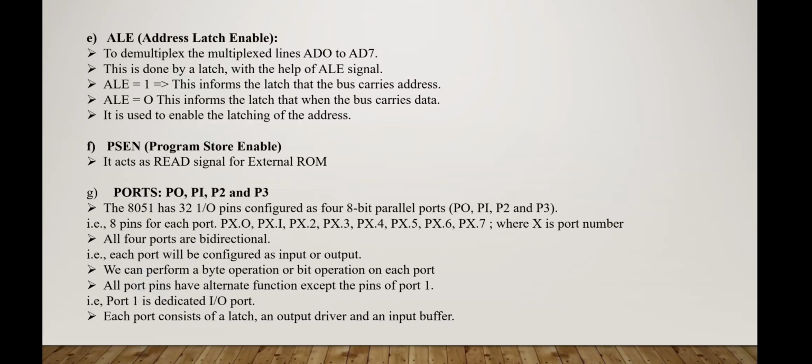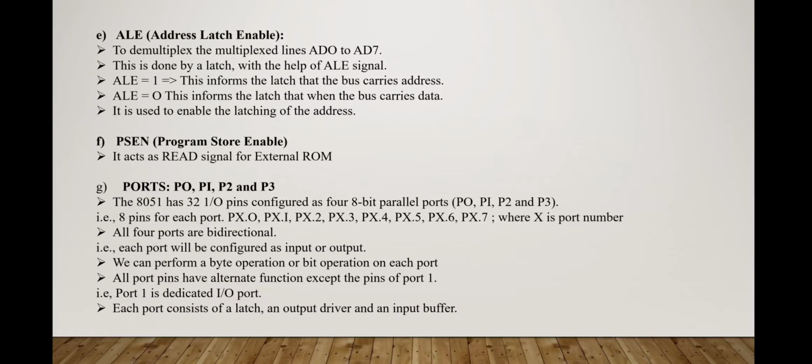Okay, then next is program store enable, PSEN. It acts as a read signal for external ROM. So if this program store enable is enabled, then only we can read the data from external ROM, otherwise we cannot read the data from external ROM.